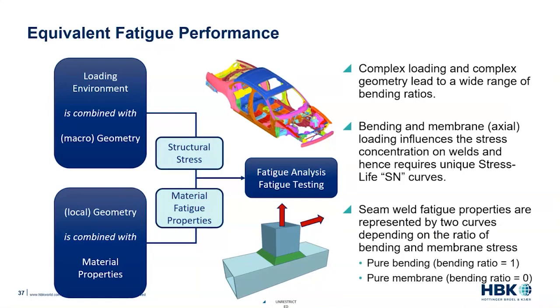So depending on the specific location and specific ratio for a fatigue cycle, we can calculate the unique stress life curve for that specific fatigue cycle, for that specific ratio of the bending and membrane stress.